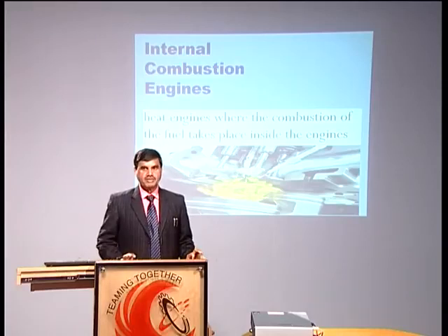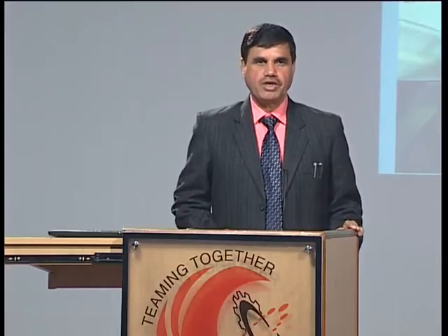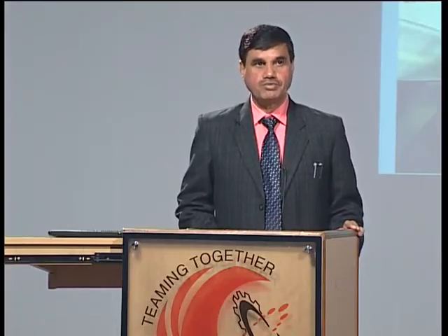The space where combustion is taking place is the clearance volume, a very small volume where the air plus fuel mixture has been compressed. If it is a spark ignition engine, a petrol engine, normally the compressed volume as compared to the total volume is roughly 1/8, meaning after compression the volume inside the cylinder where the flame is visible is roughly 1/8 of the total volume of the cylinder.